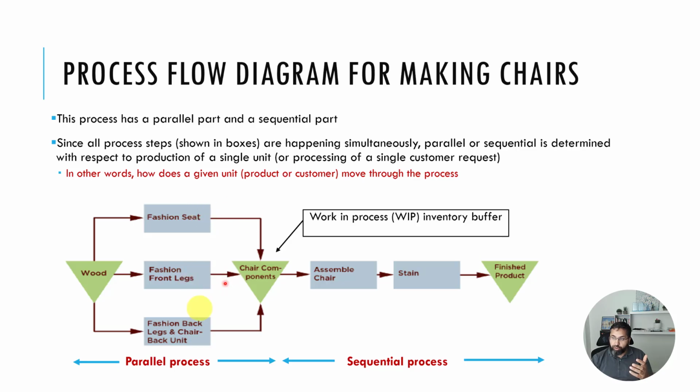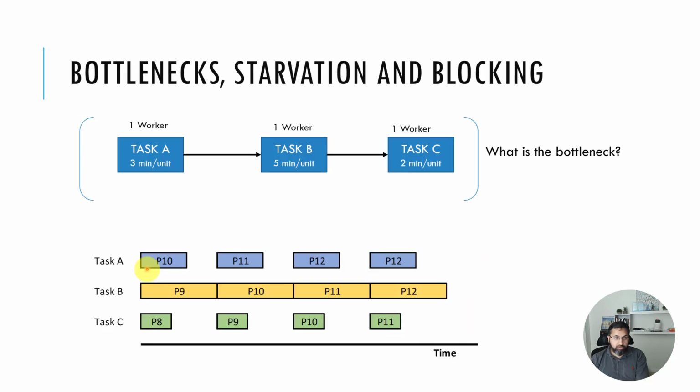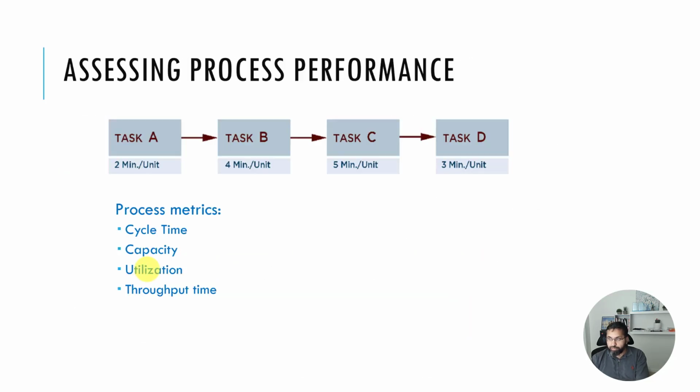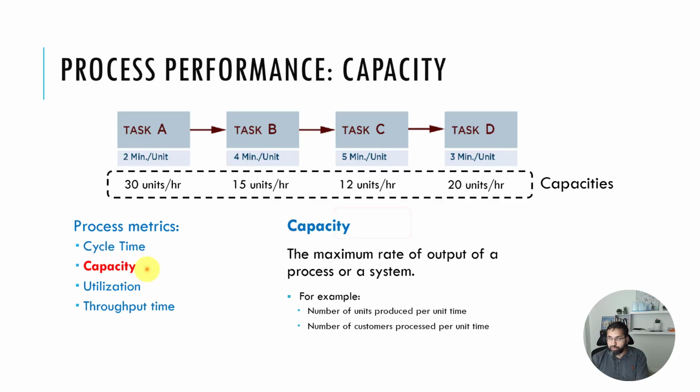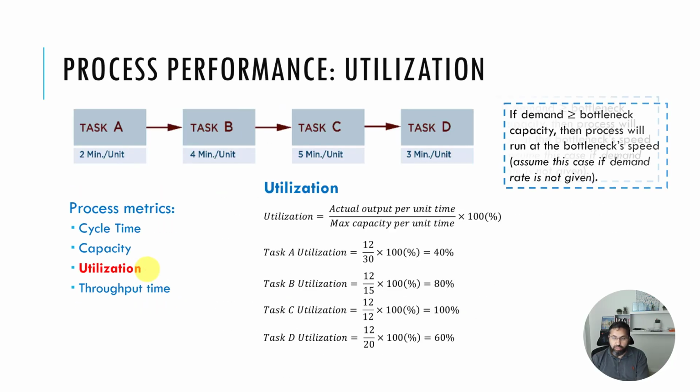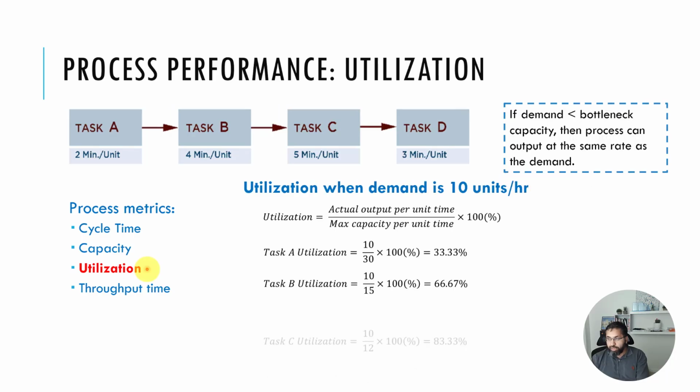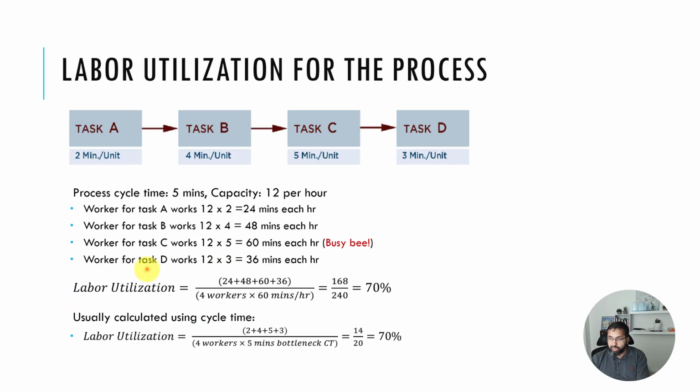It's called a converging point, where different paths in the process converge, and now you're going to have just one path forward. And this here is a diverging point, where you have WIP of wood to feed these different processes which work at different speeds. Okay, so converging and diverging points, these two points here are cases where people will often add a little bit of WIP inventory, just to decouple the steps and make sure that variability in one does not affect and starve the next step.